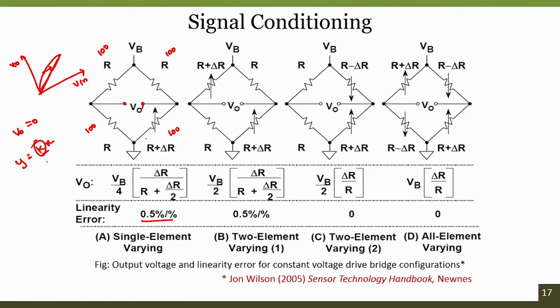What do I mean? Imagine k is 0.5: for an input of 1, y should be 0.5, and for an input of 2, y should be 1. But if for an input of 1 the scaling factor is 0.5, and for an input of 2 the scaling factor is not 0.5 and is changing, varying with respect to the input, then it is not satisfying the principle of scaling, which means that it is nonlinear. That can be simply understood because k should be constant. That means y should always be proportional to x. By observing this, if this particular condition does not satisfy, we can simply say the system is nonlinear.